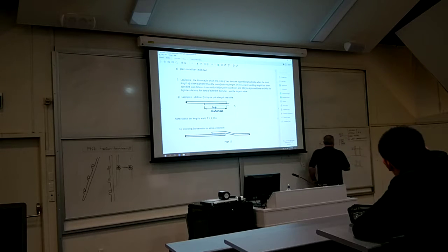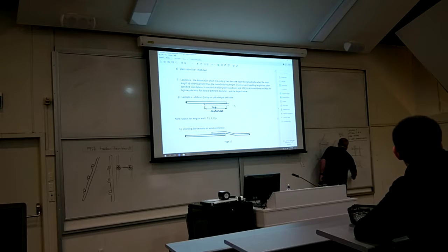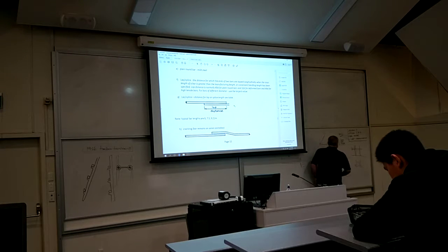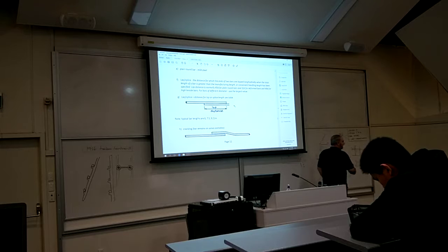However, when you come to the end of a piece of reinforcing, and it comes along like this and down like that, like your one does, some students last year carried the bar on until they got the minimum lap out of all of that. That is wrong. The bar will stop right there.